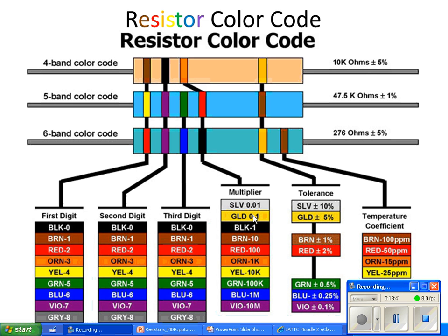So if you write it down: black, brown, red, orange, yellow, green, blue, violet, and then add gold at the top and then put silver on top of that, you can go back up as though you were going down the engineering notation chart. At your base unit, you have 10 to the 0. One below that, we're going to assume in this case we have 10 to the minus 1, and silver is 10 to the minus 2. Those won't come up today. They might come up some other day, though.